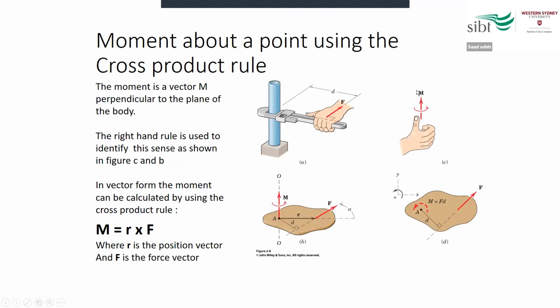Also, in lecture 3, we started getting some knowledge about the moment, how to find the moment. We knew that to find the moment around any axis using a force, we simply multiply this force by the distance between the force and the point of rotation. This distance must be the perpendicular distance of the force, which means that the force must make a 90 degree angle.